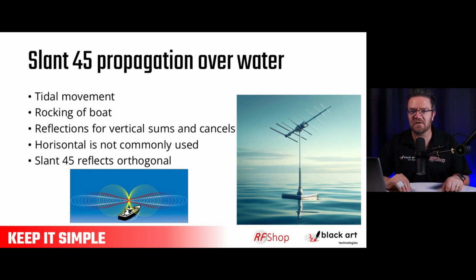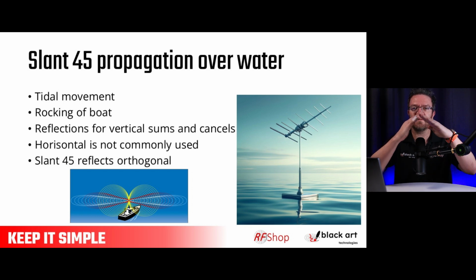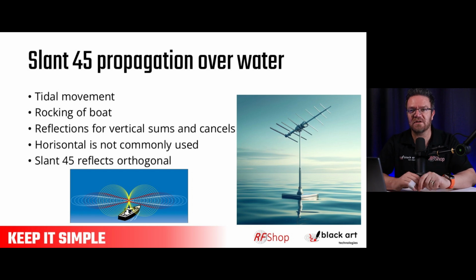Now, if you have cross polarization discrimination, in other words, you are not so effective in your orthogonal direction, which is what the typical dipole or LPDA would be, that helps a lot, because suddenly you can reduce your sensitivity to reflection. It's a simple trick. It's a very powerful trick to use, but you need to know the fundamentals of your antenna design. There, go. Good.